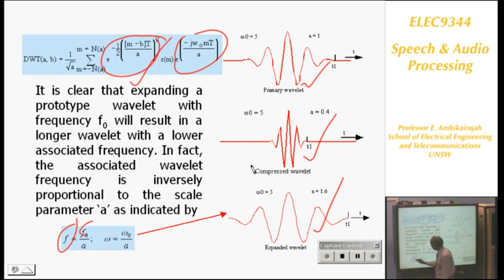You find out what your mother wavelet frequency is, that's your center frequency, 5 Hz. Dividing by A then gives you the actual frequency that you are interested in. So A is called the scale. We call it scale. It's not a frequency. So when you plot time-frequency analysis, in wavelets you normally plot time and scale, and you convert the scale into frequency by using that formula.